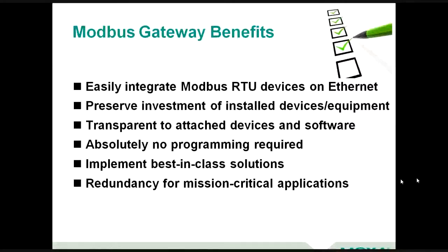Just to summarize, I hope you all got something out of today's webinar in terms of some of the things you can do, by learning from what we've been able to share and some of the experience we've gained working with serial ports and specifically with these industrial protocols like Modbus. Gateways give you a really easy way to take those RTU devices and get them on Ethernet. You don't have to replace those devices and buy new ones. In some cases, like the Schneider power meters, you can't get them with Ethernet.